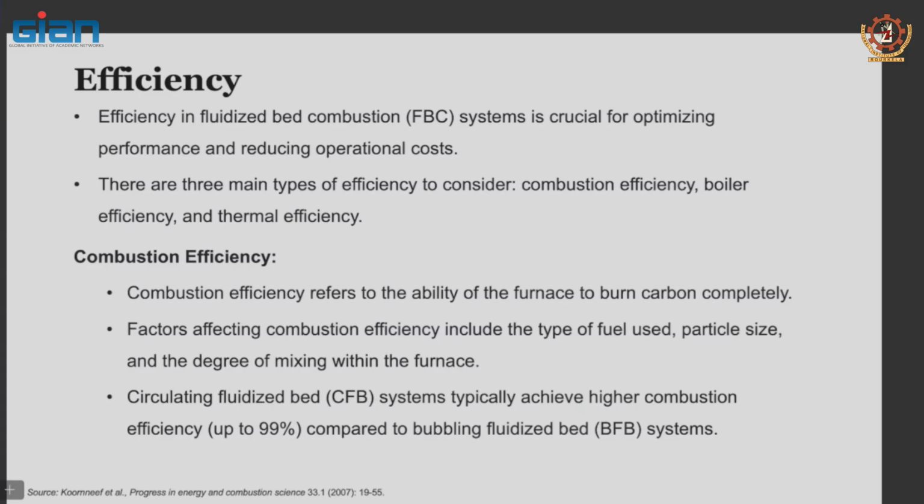So I was talking about efficiency. We talked about how boiler efficiency could be high, but the overall thermal efficiency of the plant, because of what I showed you in the Carnot cycle example, is limited: you have to condense the low quality, low pressure steam, and then you lose a lot of the energy.